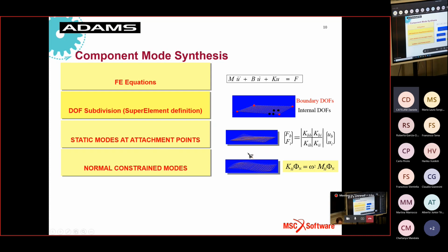And this information is stored during the analysis, and you have the stiffness matrix and mass matrix stored from this kind of simulation. Next, the finite element code automatically attaches the 4 nodes to the ground and evaluates the dynamic modes, that is, evaluates the frequencies of vibration of this plate, evaluating the stiffness matrix, the mass matrix, and the frequency of each mode, and stores also this information.